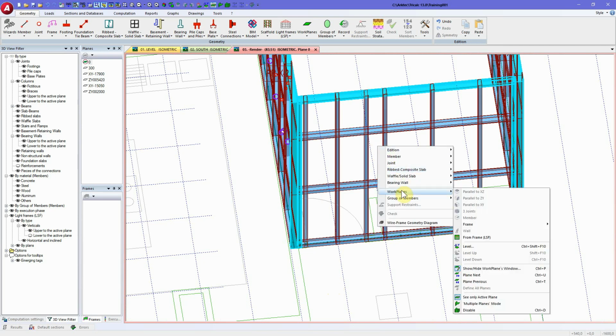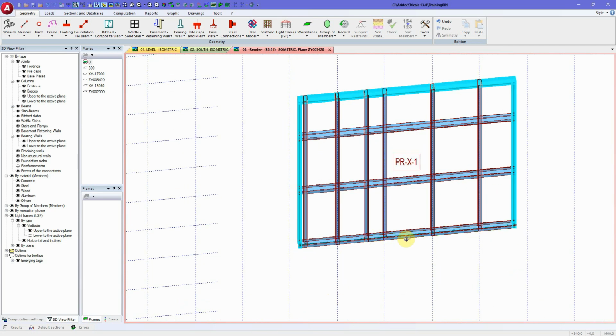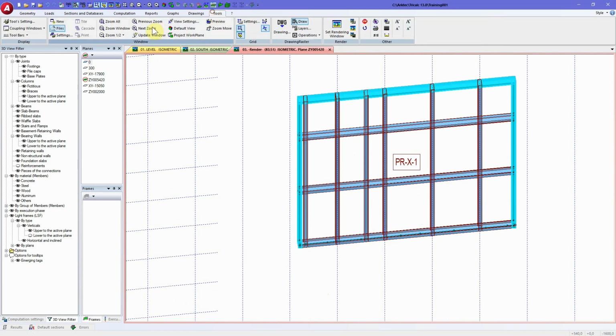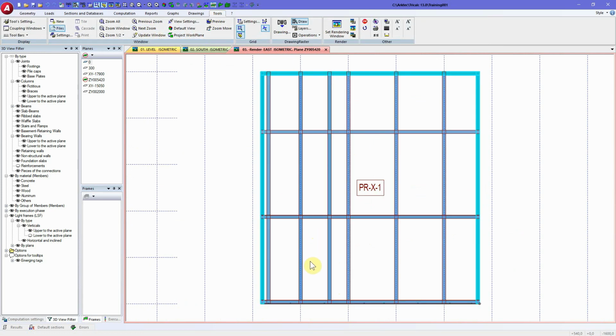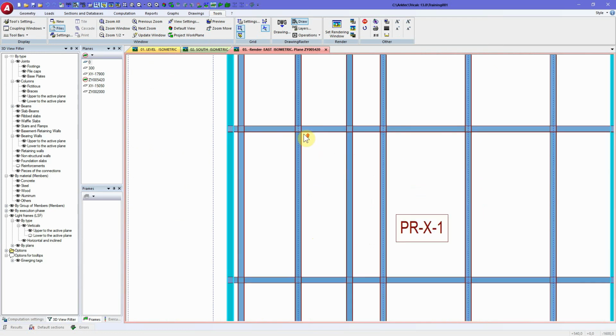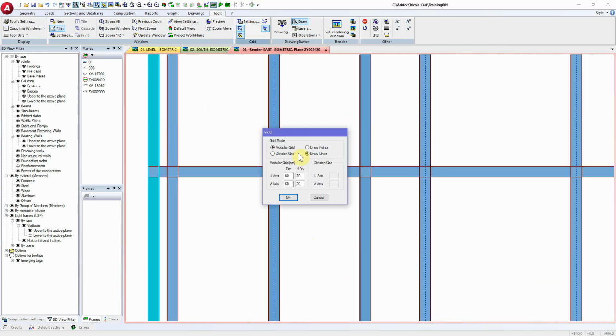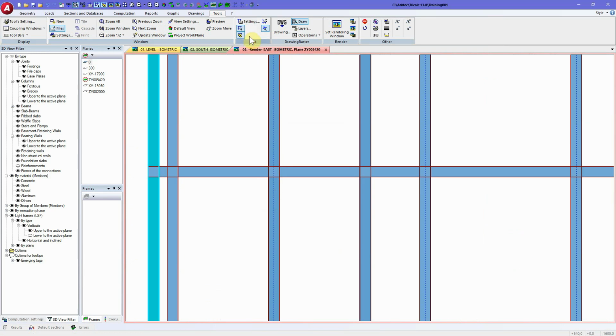Now I'm going to go to the work plane for visualization, select the work plane of this frame. We can project the work here. Now I just need to divide the elements that I want to split, the elements that I want to delete. So for that, I'm going to increase my precision here to 1 centimeter with my grid line, and I could disable the snapping,